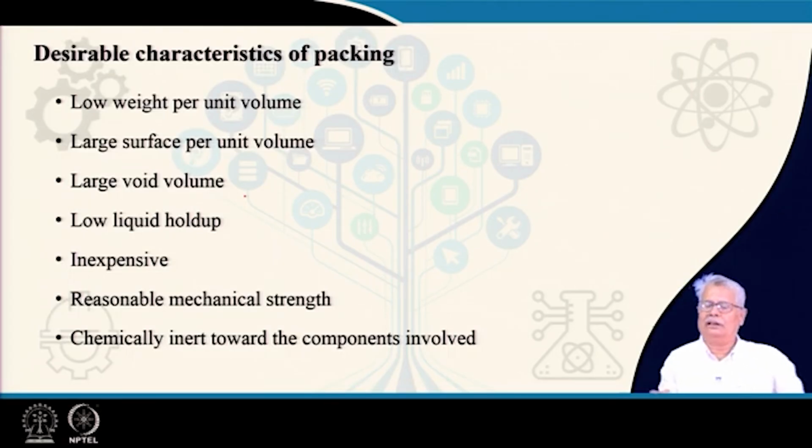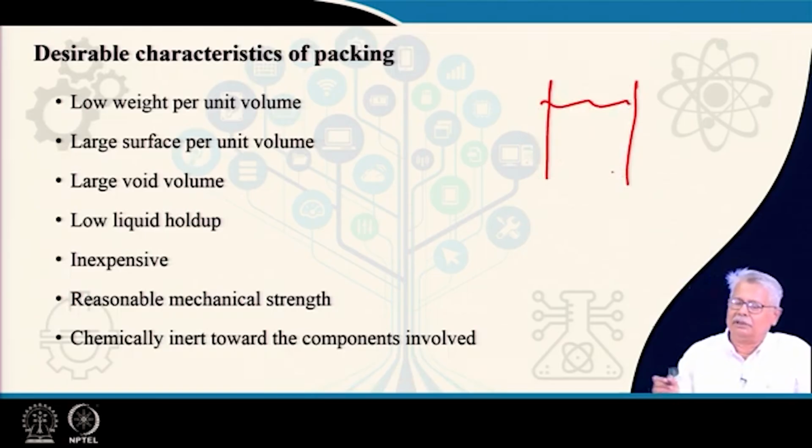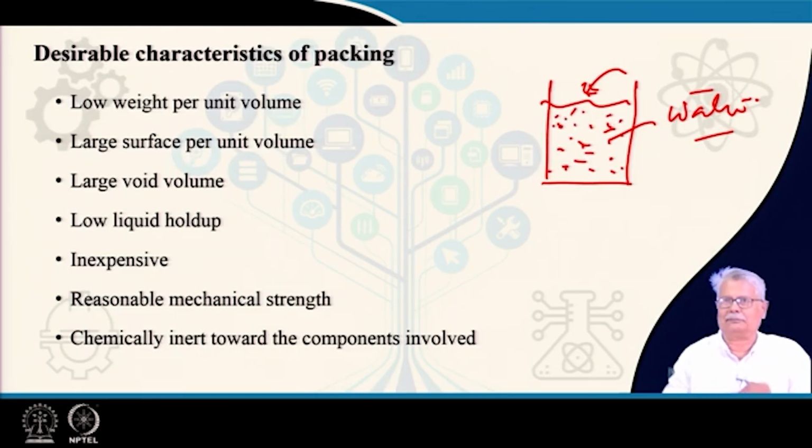You can have a tower which is filled with liquid. If you are sending random packings, you will be dropping the packings into, possibly, water in most of the cases, and the packings would come and settle down at the bottom, and gradually a bed builds up like this.